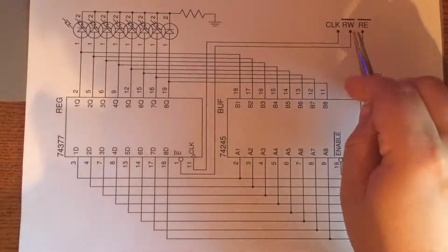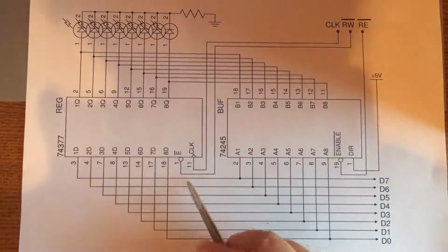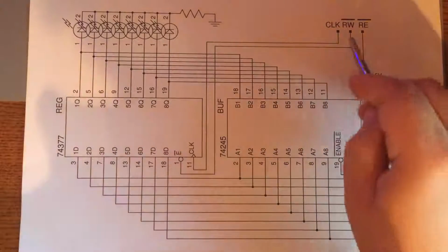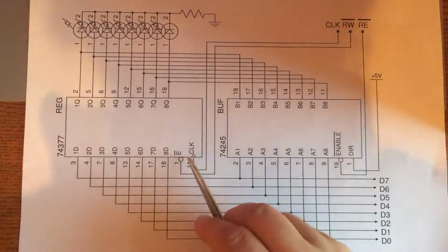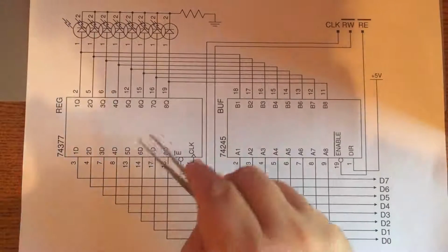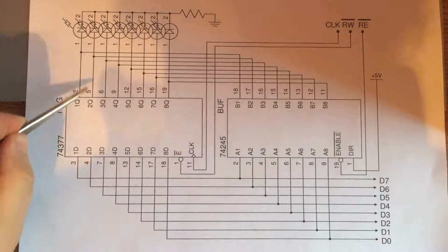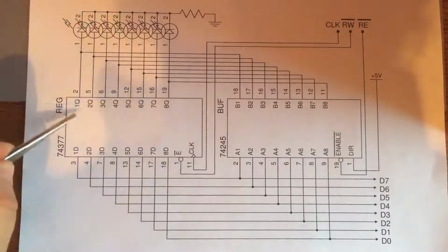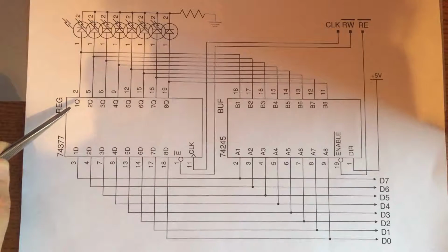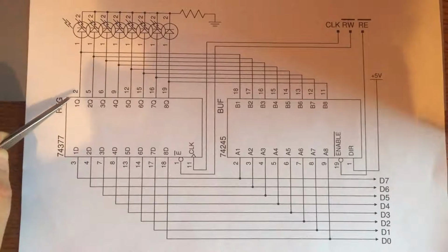Those inputs will get stored into the register if this enable signal, which is an input control signal, the write signal for our register, is asserted at that time. It'll arrive on the next rising clock edge. When that happens, whatever is on the bus at that time will get latched into the register, and it will be output immediately onto these Q lines, onto the green wires in my circuit. That's because this chip doesn't have an output enable. The output is always enabled, and that's what we want.